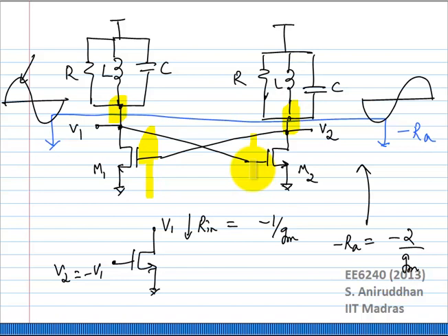The other kind of mismatch which is available is noise. Okay? There will always be noise from each of these two, M1 and M2, creating small mismatches between the two sides. It's either noise from M1, M2 or noise from the LC tank. Now, obviously the noise created mismatches will be extremely small, and they will actually start up the circuit when the loop gain is very large. Okay, if the loop gain wasn't large enough, you may not see it oscillating at all.